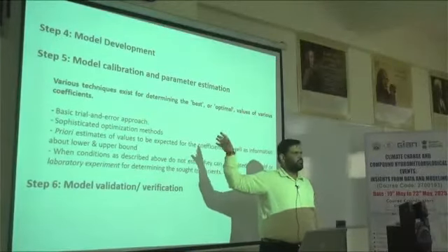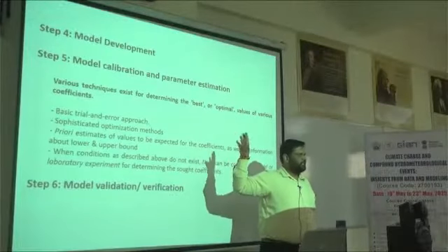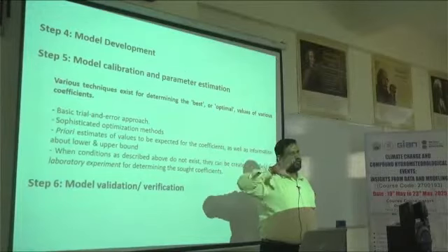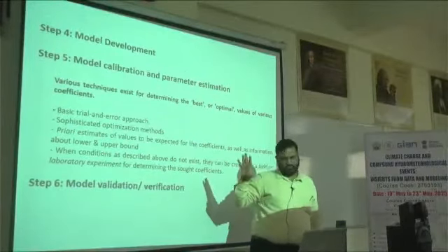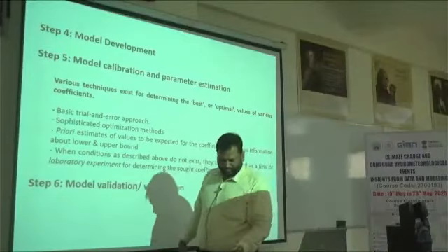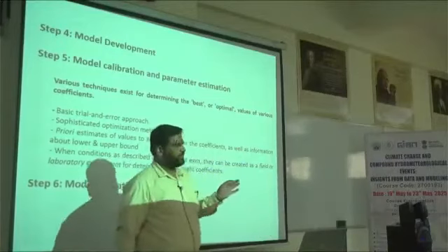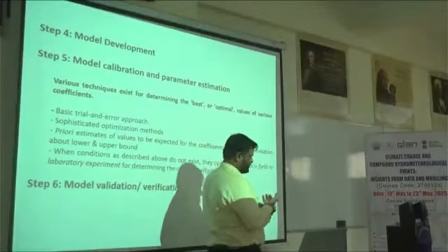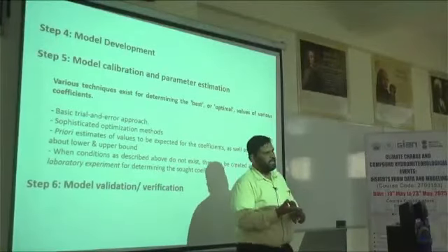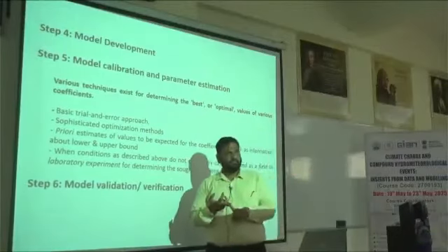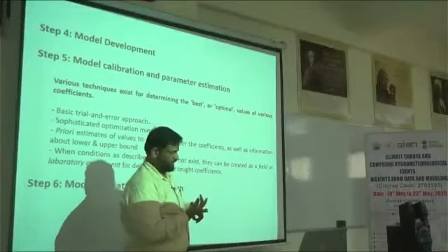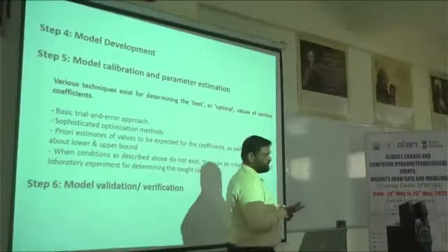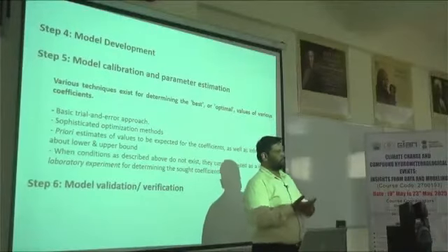So that is one of the most tricky parts. That is why you require complete knowledge of hydrology. Otherwise, you won't be able to do calibration. If you don't know about the curve number method, then how would you identify it? Curve number is a function dependent upon the land use as well as the soil types and the management practices, whatever management practices are taking place in your catchment area. So you must know the hydrology as well as your catchment area.